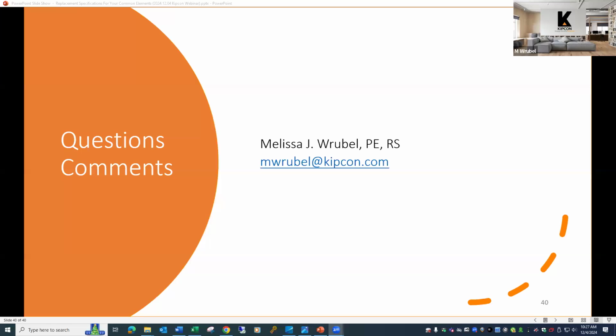Do you do the pre-bid walkthrough with each individual contractor or all contractors as a group? You can do it either way, and I've been involved in both. You can do a general walkthrough and invite all bidders. That's why it's important to have a sign-in list so you can see who actually attended the walkthrough.